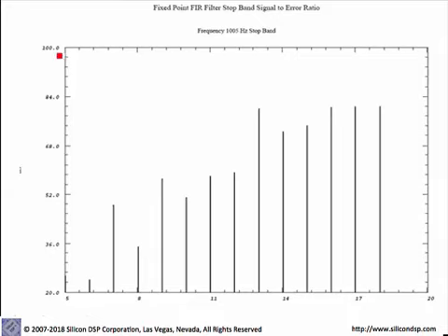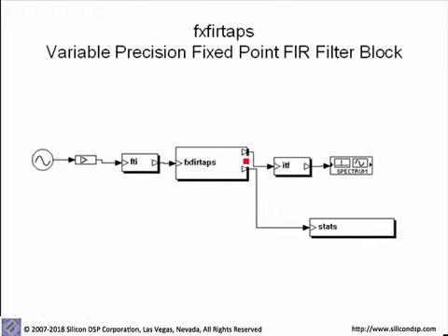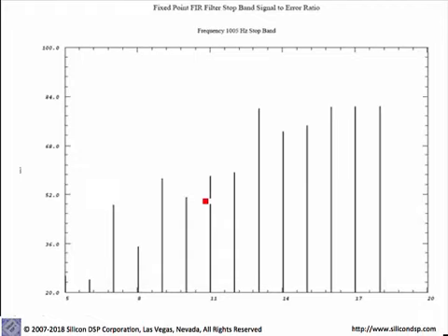And here we're showing the signal to error ratio. This is the ratio between the strength of the signal here and the error over here. So we're actually measuring the RMS power over here and obtaining the ratio between the RMS power here and the error here and plotting that in dBs.